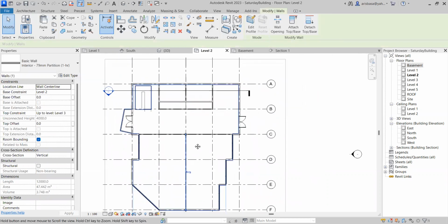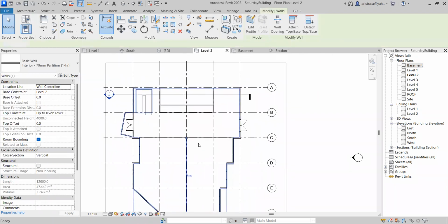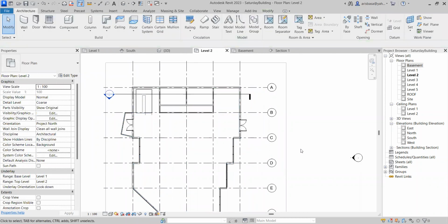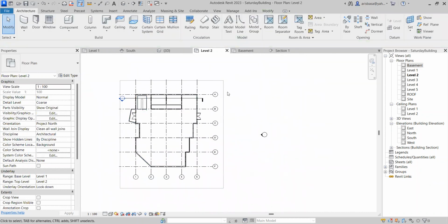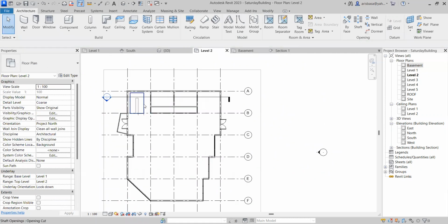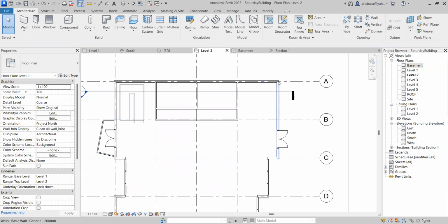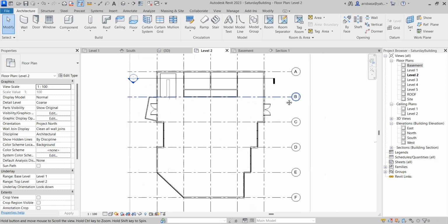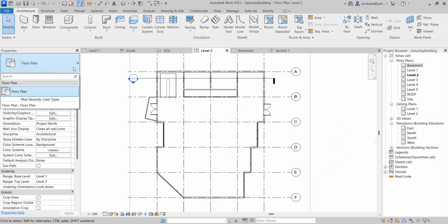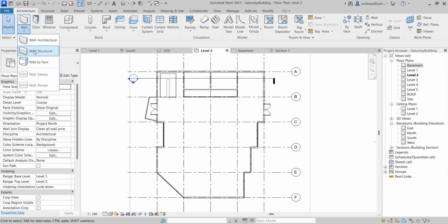In each floor, if you want different layout on each floor, it's up to you. But use the gypsum wall and make sure that your staircase is fine. Do not create additional staircase yet. We will do that next week. Okay. We will use what we call multi-story stair. Okay. We have a 79 mm gypsum partition wall.